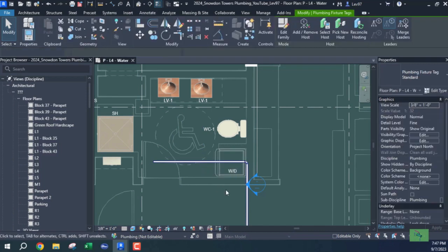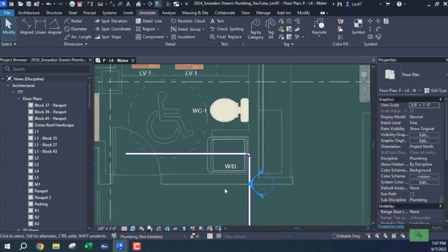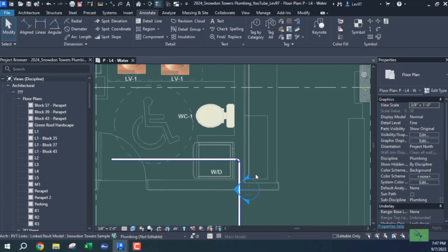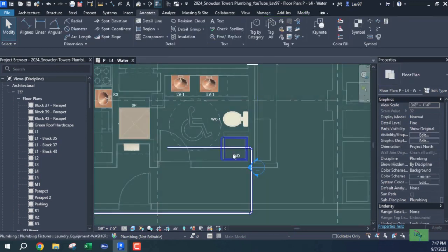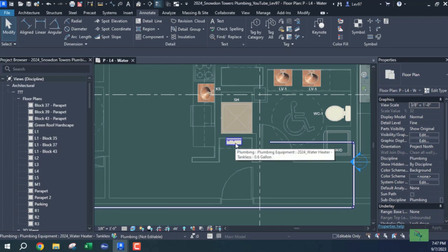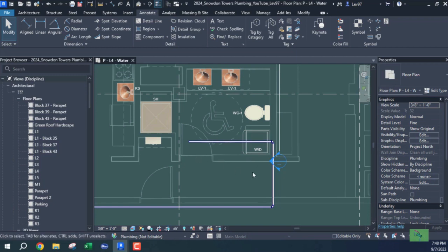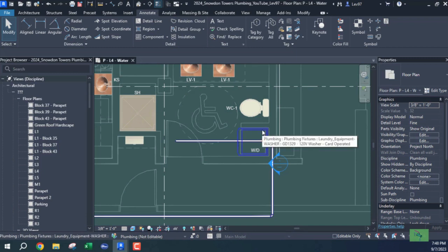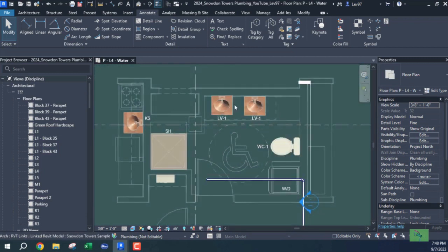I can put it inside. I think it's okay. So I have that. I'm gonna scoot this over just a little bit to the right, and so I'm going to use my cold water to supply this tankless water heater, and also I'm going to branch off and supply cold water to the shower and to the kitchen sink. Okay, so right now I'm in the ceiling space, so I'm going to have to drop down. I'm going to use a T to drop down and pick up washer, dryer, water closet, and the 2 lavs.